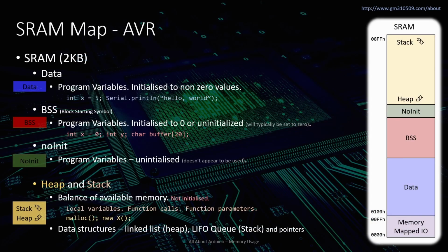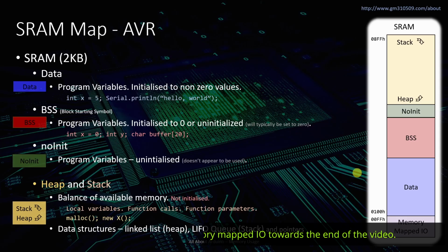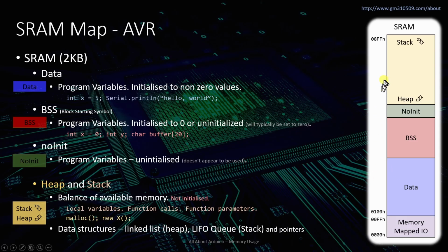All right, so drilling into that yellow region, the RAM, that's further broken down like this. So I already talked about the memory mapped I/O, this purplish greyish section at the bottom here. And so I won't really look at that. You can look at the data sheet for how that works. But then the way the C compiler organises the rest of the memory is it uses these sections here. And so then there's these two here, the data and the BSS.